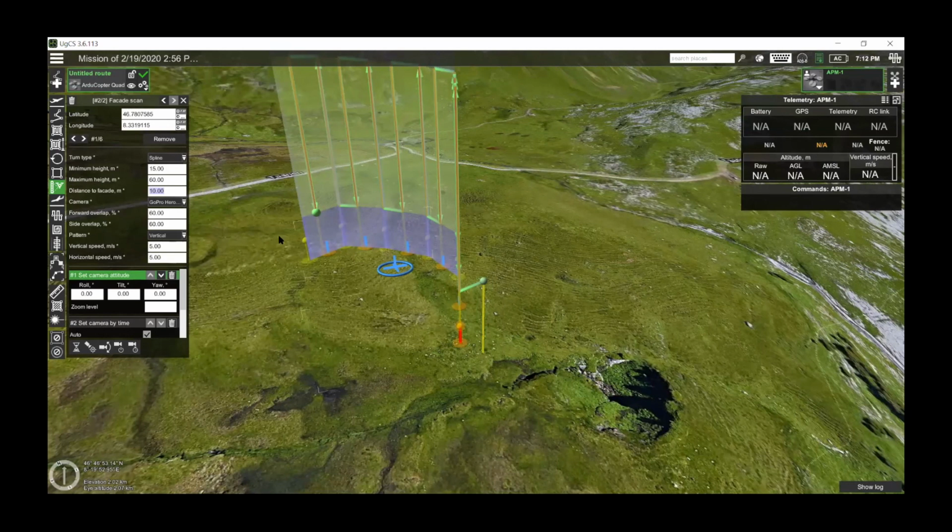But 10 meters is the optimal, because if you choose a closer distance, you need to remember that standard GPS accuracy is floating, and sometimes it can float up to 2-3 meters, and flying some 2 meters from the facade at higher altitude and in windy conditions can be pretty dangerous. So for safety, we suggest you evaluate very carefully how you set this parameter.